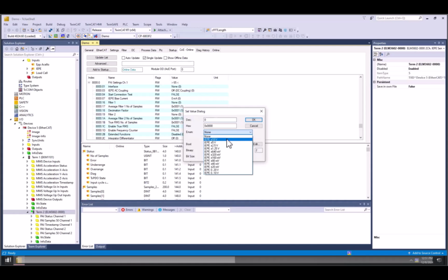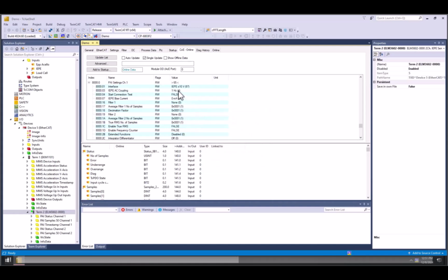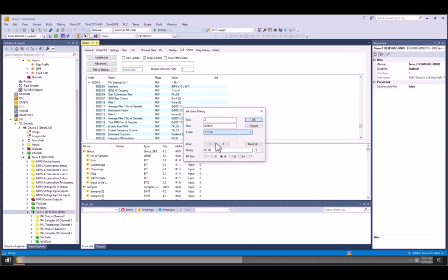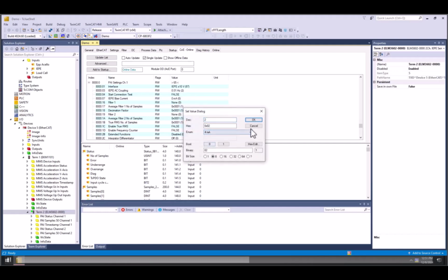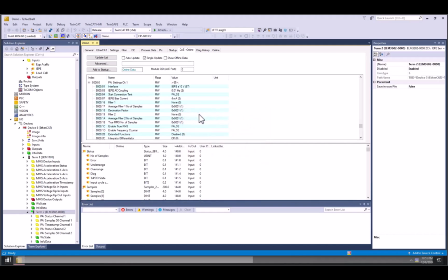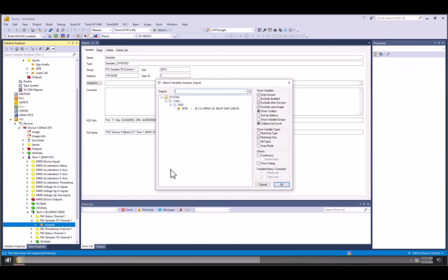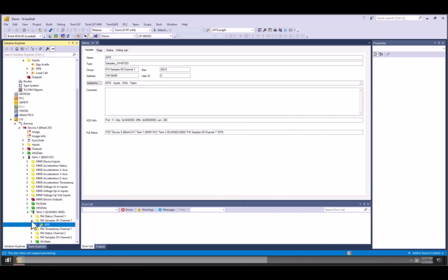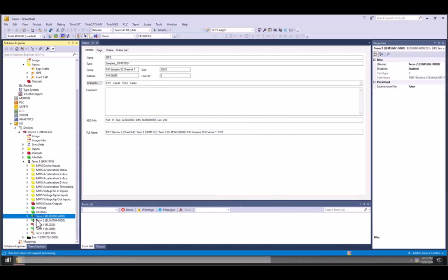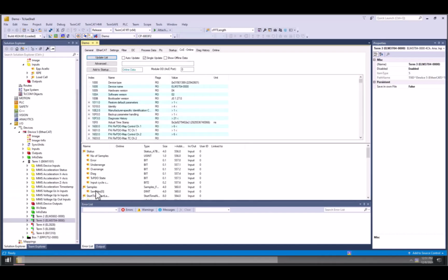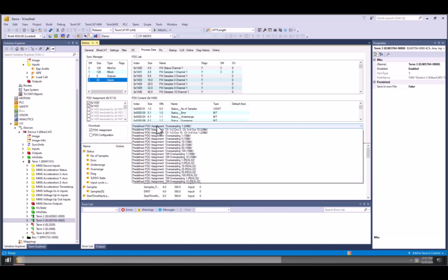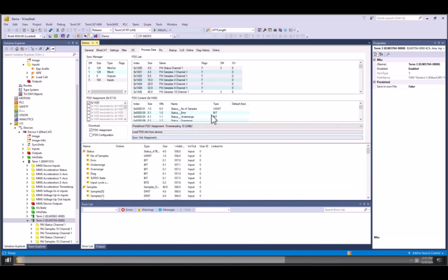Now I can go in, and this is the interface to specify your measurement range, your interface. In this case, my IEPE AC coupling and my bias current as well, for allowing my vibration sensor to function. And then I'll also link the data object to what I had defined up top with my task. And I'll do the same process with the other terminal.